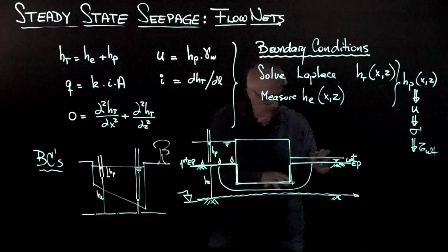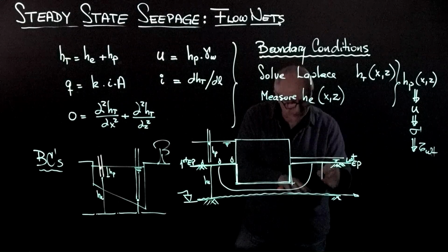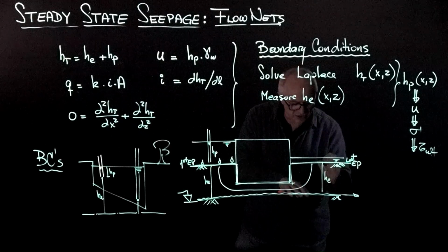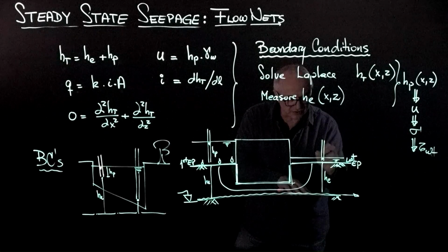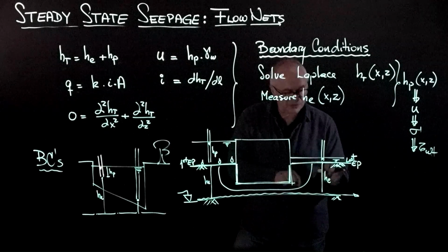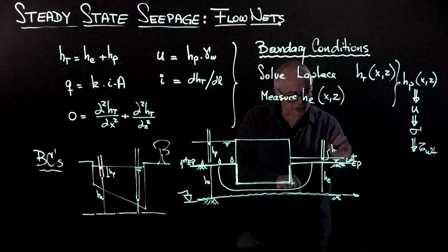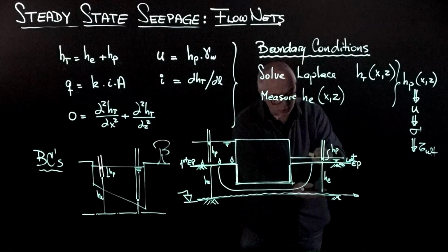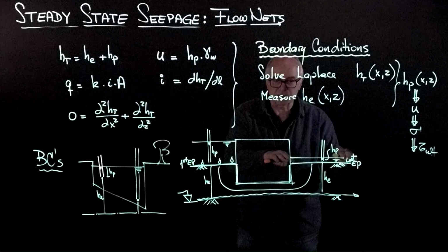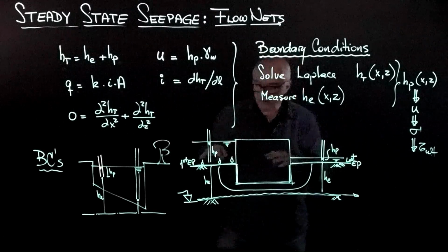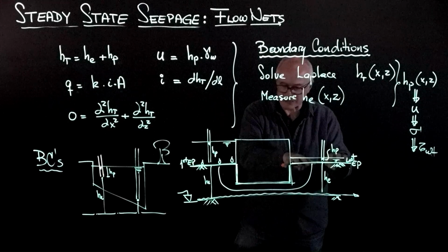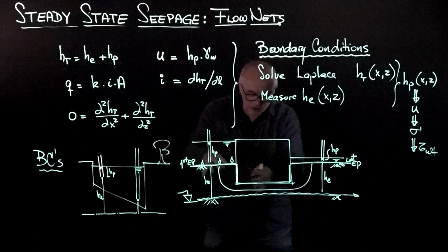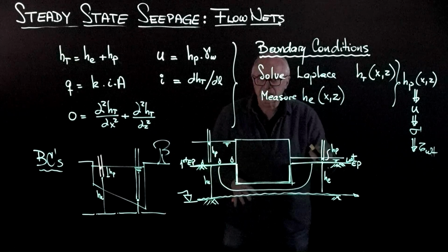I can do the same with the last equipotential. This would be the H elevation at this point, and if I place a pipe, it will only rise to this water film. And so this elevation plus this H pressure gives me the total energy on the last equipotential. And that's what I know. I start with this energy, I will end with this energy level, and I will gradually lose that energy level from the inlet to the outlet.